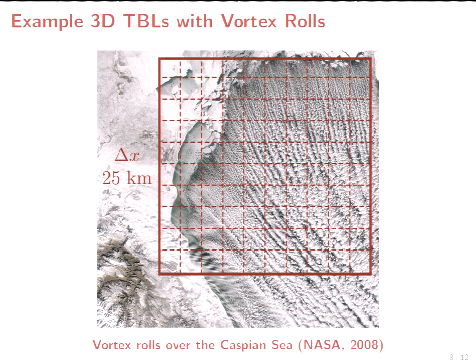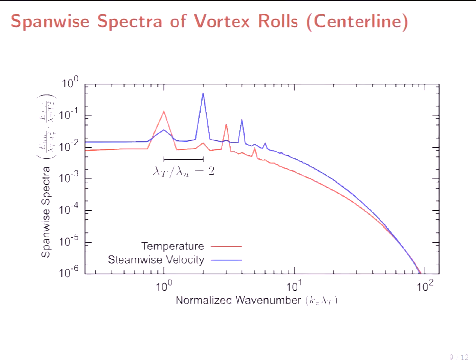So this is a classically well-known example that when you grid, say, in turbulent flows, you very often have smaller spanwise spacing, because these organized structures are preferentially aligned in one direction rather than the other, and to resolve them, you need to consider this effect. Okay, so like in the example I showed before, this is a very large aspect ratio domain, and to be able to resolve these large-scale organized structures, we want to see what's necessary.